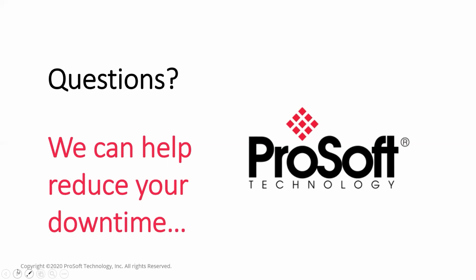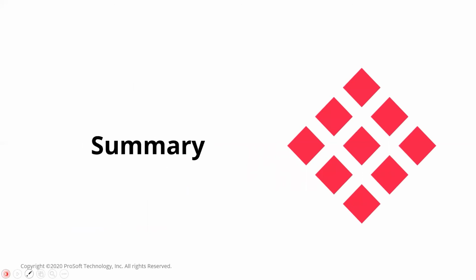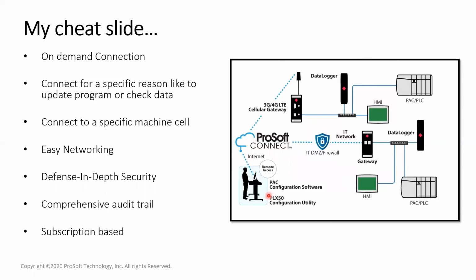Okay. Another one I have is, with remote access, can my SI change PLC code and HMI screens remotely? Absolutely, yes. So the entire point of remote access is, if you look at this slide, the idea is to ensure that they have the same experience as if they're sitting in front of the machine. They are able to remotely connect, provided they have the right security clearances and they've been given permission by the end customer. They can connect to that specific automation device, whether it's a PLC or a drive or an HMI, review the code, review the problem, and then fix it if that's where the issue is. Whether it's downloading firmware or downloading the program, they can certainly do that remotely.